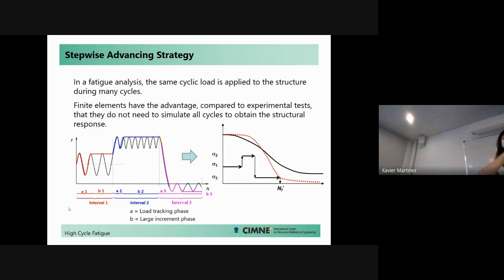With that value for the entire geometry, you go inside this plugin which solves fatigue in a commercial way, and it will output the life expected for that component. Of course, it has several reduction coefficients, for instance, if you have welding, or specific features that affect your fatigue behavior.